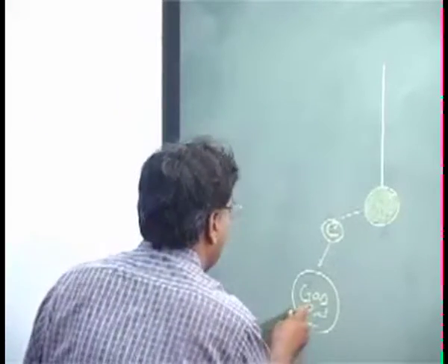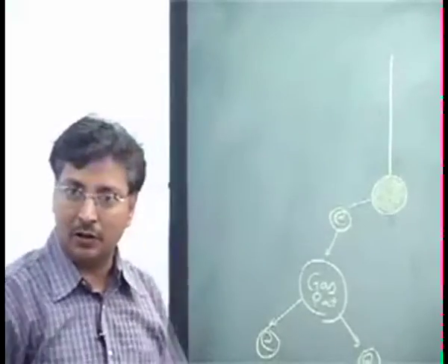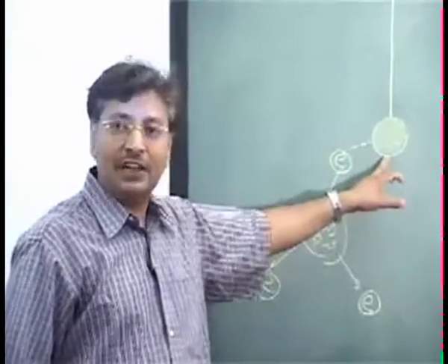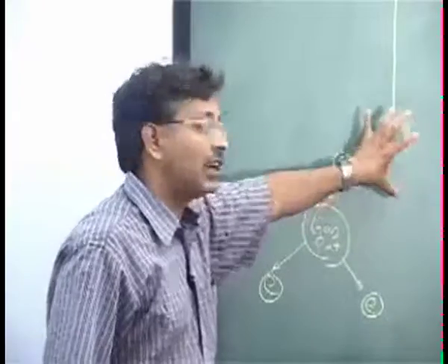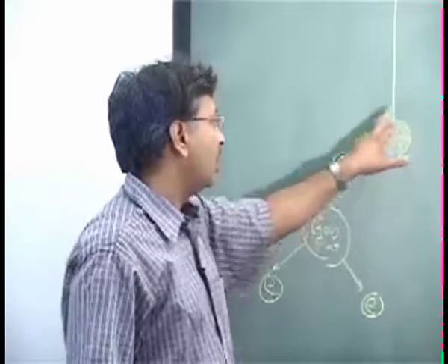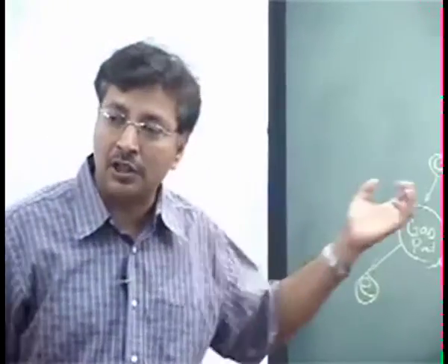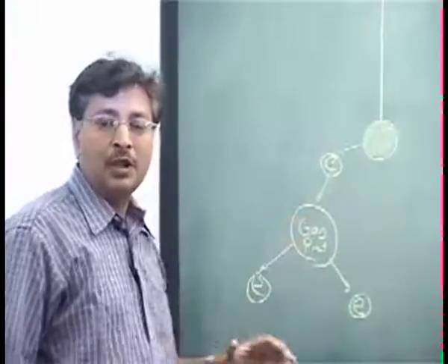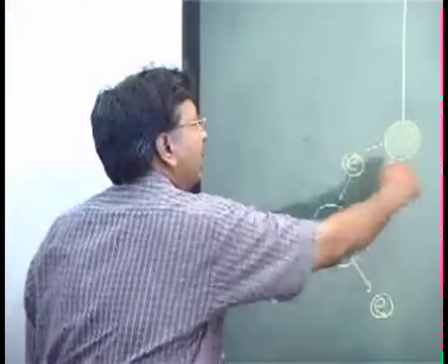So in the process they can knock off some more electrons from the gas as they go away. Again, they can knock off more, but as they go away they also lose their energy because they are getting far from the electrode, and the numbers will reduce. But this can be very significant very close to your electrode. These gas particles will become positively charged, and they will rush towards the electrode and get discharged. But the electrons which got free will continue to move away, and their energy will reduce. Once their energy is reduced, they cannot do more charging and knocking off of electrons from the gas particles as we go away. But in this area, they will do a lot.